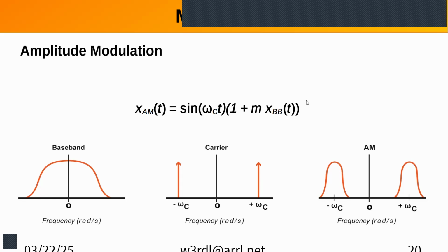And then when you actually have modulation for AM, you've got this kind of wave shape. You got the carrier and you got the sidebands on either side of it up here, but you also got this imaginary negative image down there too in the mathematics world. It starts to pop up when you're doing digital signal processing because that's all mathematics. So you have to take account for those things.